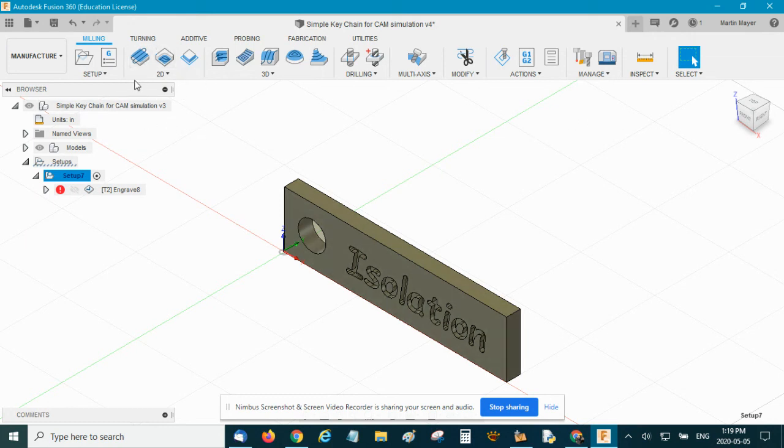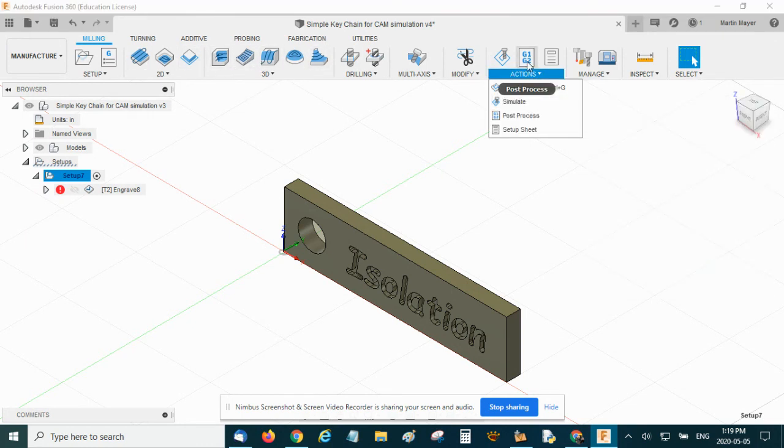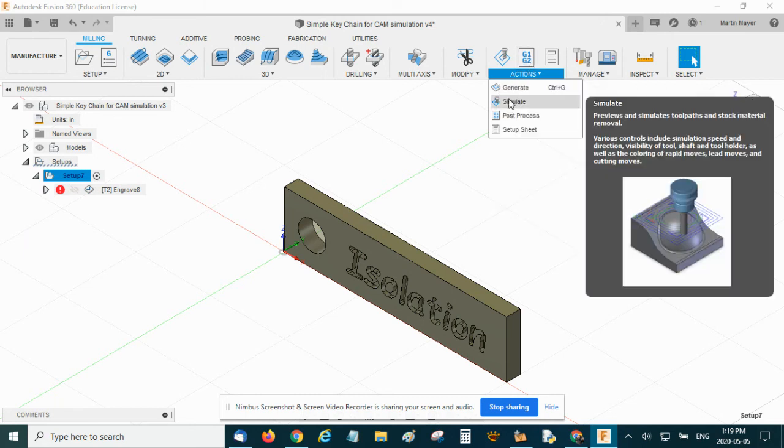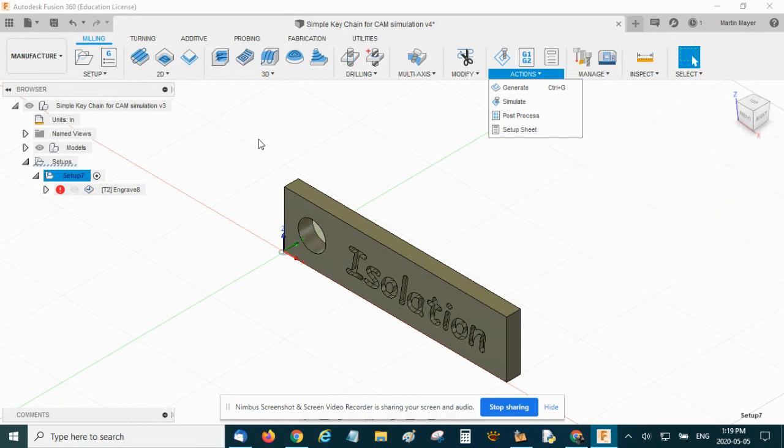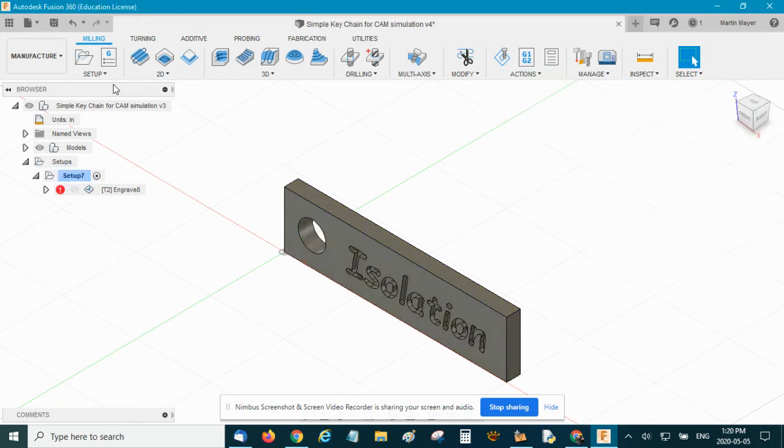When you select the manufacturing feature, a whole new menu system pops up, and it's essentially 3 things we need up here. We need to do a setup, we need to pick what kind of cut we want to do, and then we're going to go over here. We're not going to run in our G code just yet. We're just going to run a simulation, see what it would look like if we actually cut it on the machine. I've already done some of the setup, so it's a little bit different,